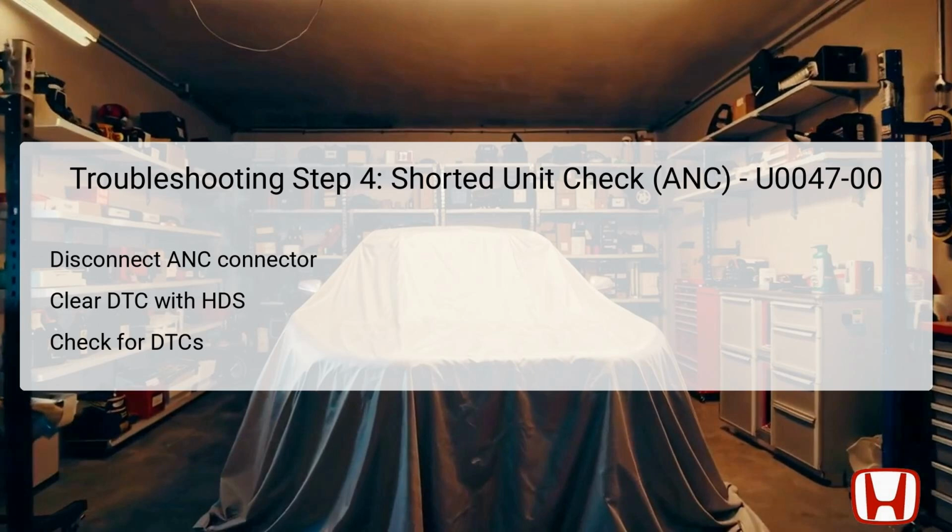After the connector has been removed, switch the ignition back to on mode and clear any codes using the HDS system. As before, allow the vehicle to turn off and return to on after a wait period of 6 seconds. Checking for DTCs with the HDS will confirm if the U0047-00 code persists. If so, check other electronic components to ensure they are functioning correctly in the network.